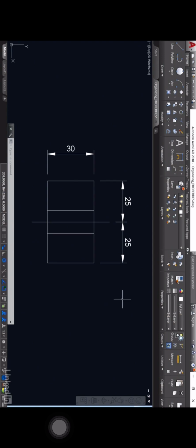You can see we've got a little side view, and we've got some dimensions as well. Now it may be when you're organizing the properties of objects in an AutoCAD drawing that you do it by object or you do it by layer. It does depend. If you're organizing the properties of, say, the dimensions here, you might want these to go on a particular layer, such as the dimensions layer.